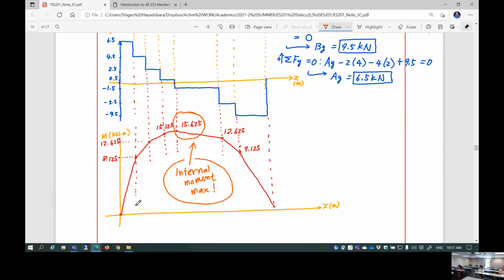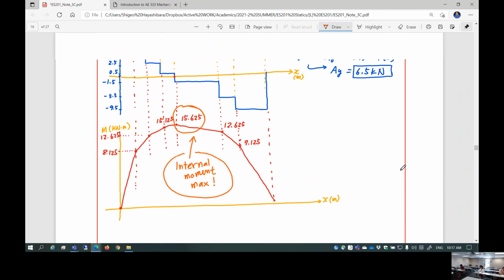Anyways, so I guess bottom line is very simple. You have to simply follow the equation, which is very simple. 2 equations. Okay, relating external loading to internal shear, and the relationship between internal shear and moment, and then if you integrate, of course, you're going to find out area under the curve to determine the jump. It's a very simple deal. So it's the governing equation. Okay. Any question here?